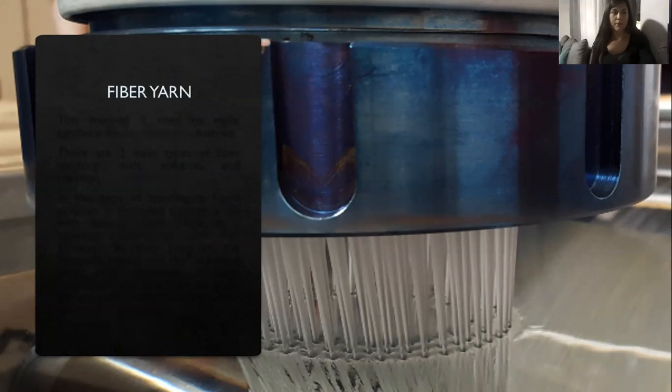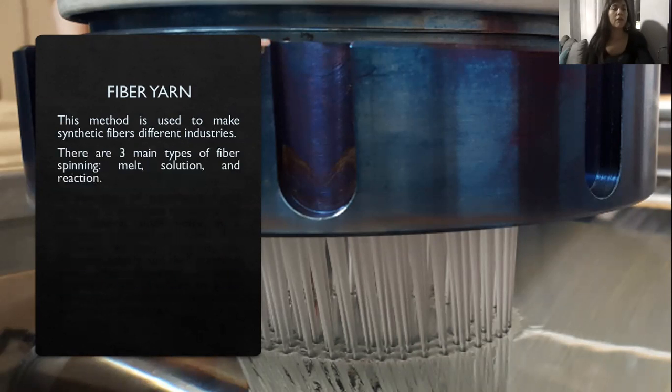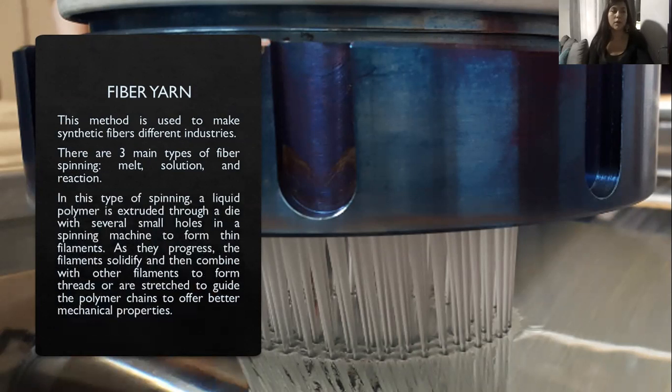Later comes the fiber yarn. This method is used to make synthetic fibers for different industries. There are three main types of fiber spinning: melt, solution, and reaction. In these types of spinning, a liquid polymer is extruded through a die with several small holes in a spinning machine to form filaments. As they progress, the filaments solidify and then combine with other filaments to form yarns or a stretch to align the polymer chains. They offer better mechanical properties.